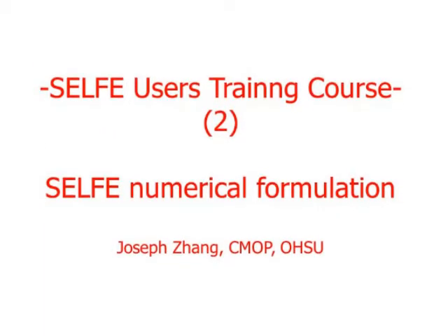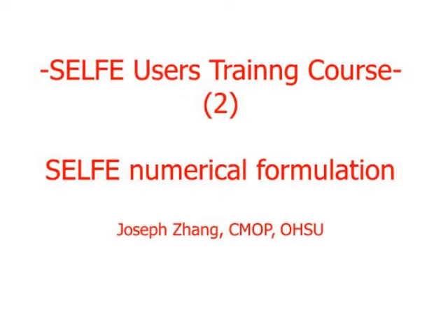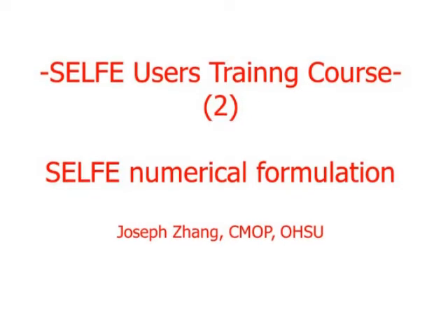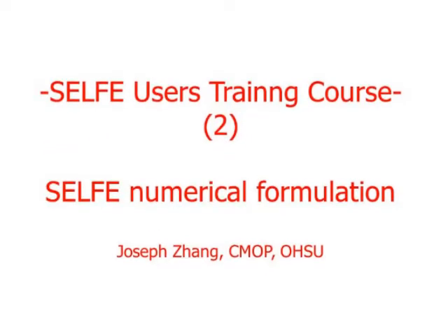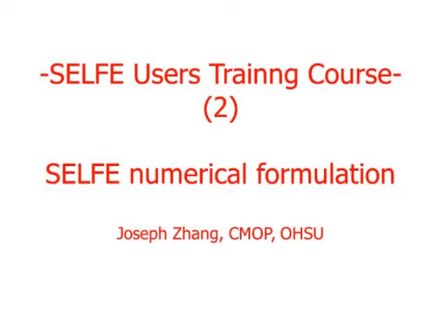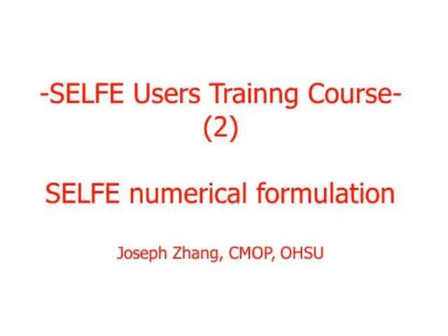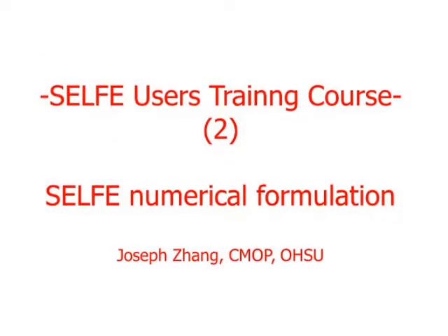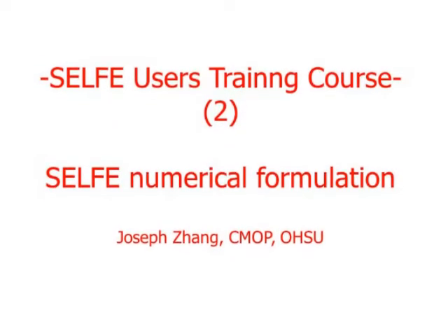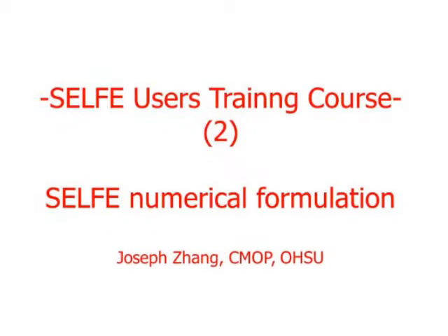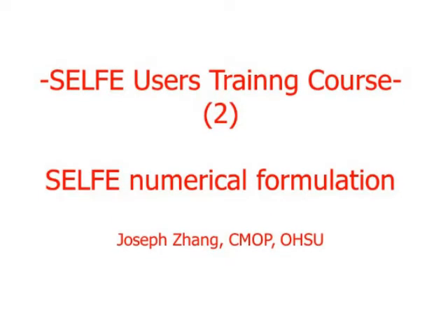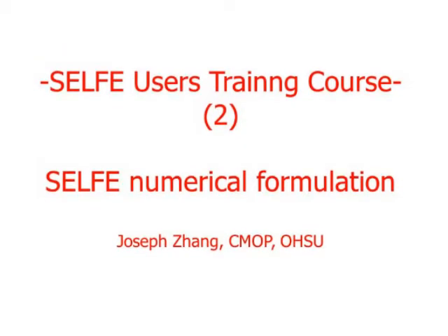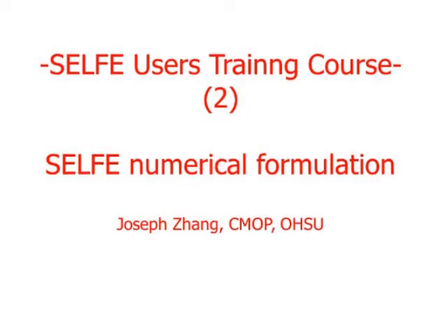After all the unknown equations are solved, the momentum equations and transport equations are relatively straightforward to solve because they only involve the vertical direction. On the top, you can see the momentum equation. Again, we grouped all the explicit terms into the bold F. And now eta is also known. So the only unknowns are inside the vertical viscosity term, and we treat that term implicitly.